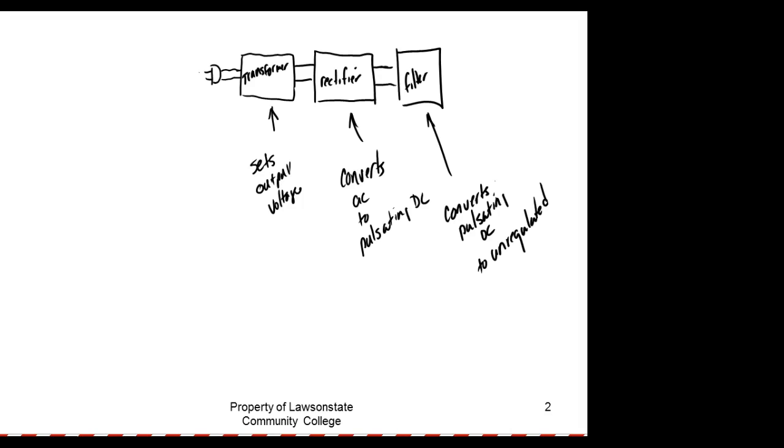Now, if it's regulated, that means I can take this right here and plug it over here. I can take it home. I can plug it in A building. I can plug it in D building. All these buildings, even though they've got their own transformers, I can come over here, and this is a regulated device. It's 20 volts, and it's going to measure about 20 volts no matter where I go, right? Everybody understand that?